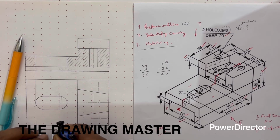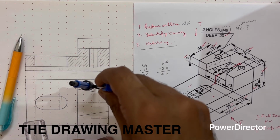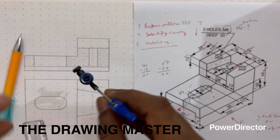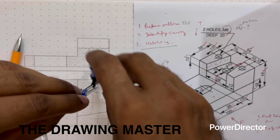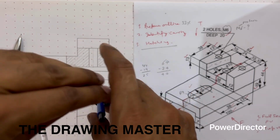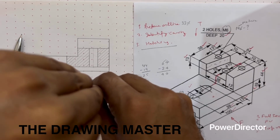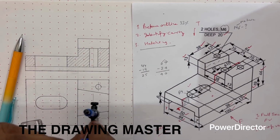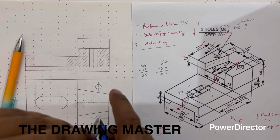It's very difficult to draw, but here you can use the Circle Master if you want. Circle Master is easily available in stationery shops. It has holes of different sizes, so you can directly draw this hole with the help of the Circle Master. So this is the hole of dia 6 for M6.